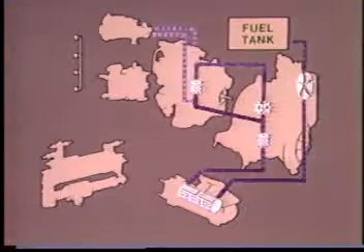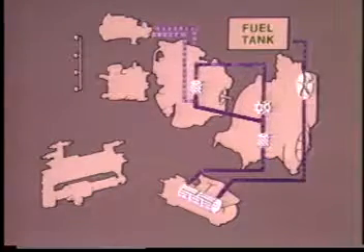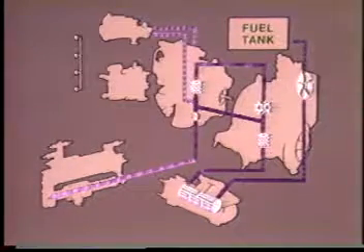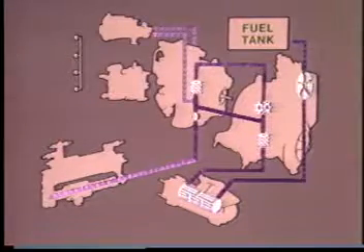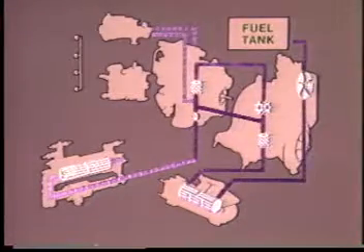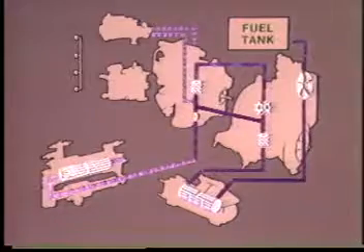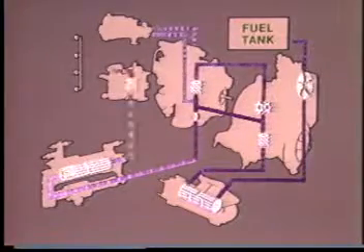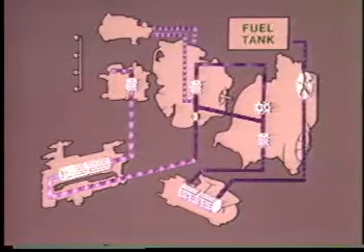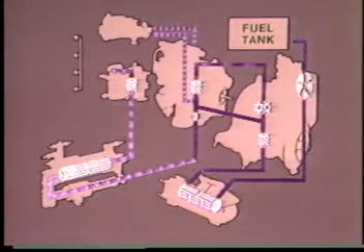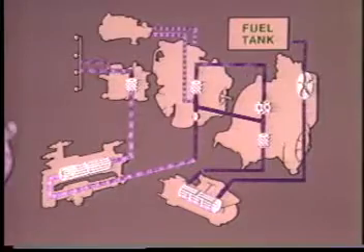From the fuel control, metered fuel is sent through the fuel flow transmitter and then passes through the fuel oil cooler. The fuel then goes through the pressurizing and dump valve. The fuel manifolds carry the fuel to the nozzles, where it is atomized and aerated for combustion.